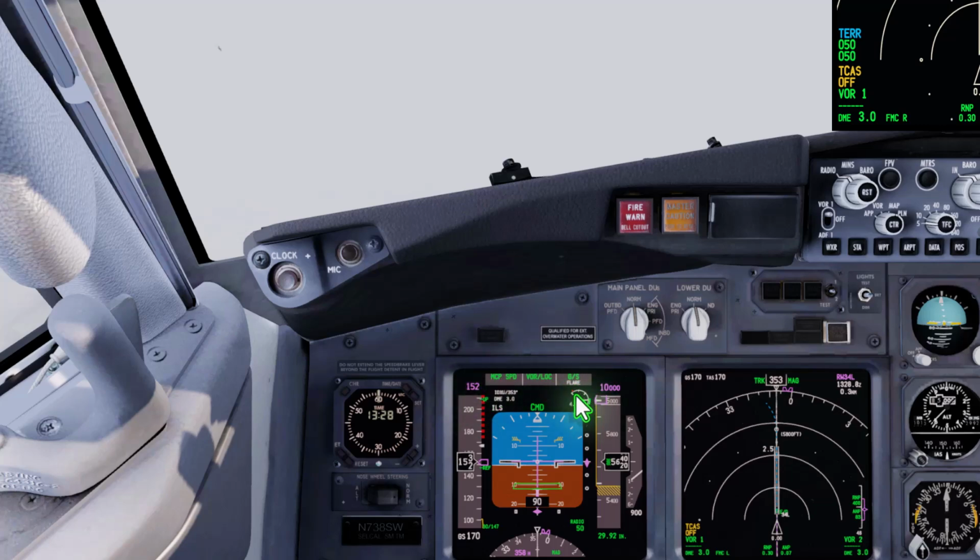Now here's what we're going to have happen. At 100 feet, the roll cue and the pitch cue are going to disappear and we'll just have the runway symbol. At 50 feet, we're going to get a green flare. And then at 30 feet, we're going to get a retard on the throttle. But our minimums, we're looking to have a minimum decision at 50 feet radio altimeter.